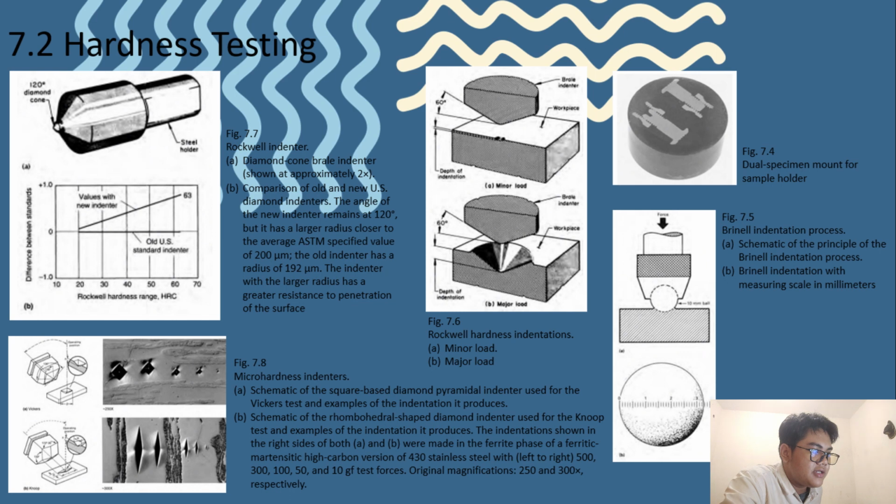There are some fairly accurate quantitative relationships between hardness values and other mechanical properties of materials, such as ultimate tensile strength and strain hardening coefficient. Hardness testing also is one of the few non-destructive tests available to qualify and release a finished component for use in the intended application.